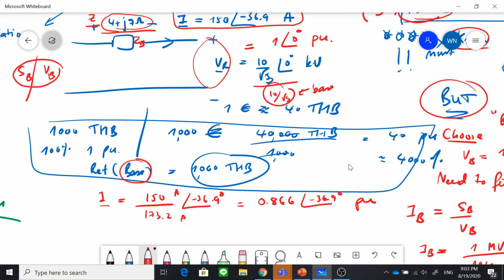So everybody knows that the S base would be equal to V base square divided by Z base, right? V square divided by Z, it is the power. Well, now we say in terms of the magnitude of the complex power, that is called apparent power. So now if you want to find Z base, the S and the V are known, we want to find the Z base. The Z base, it's what?